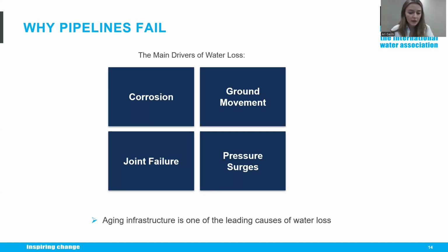And then we have mechanical failures such as longitudinal cracks or sudden pipe bursts that are often triggered by pressure fluctuations or fatigue. And of course, external influences such as traffic loads, soil movement, freeze-thaw cycles, or even earthquakes can accelerate the deterioration process.